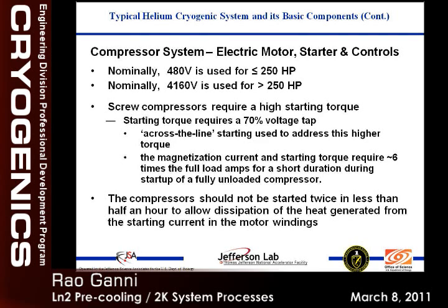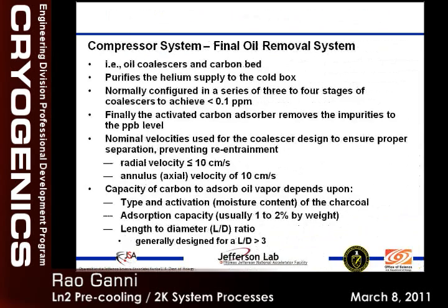And also they should not be started in less than half an hour, because the amount of starting torque is so high, it draws so much starting current into the windings, they won't cool down unless you wait. And people, if you keep pushing that button again and again, you will burn the winding. Final oil removal. Well, if you don't remove the oil before it gets to the cold box, the cold box will remove it.